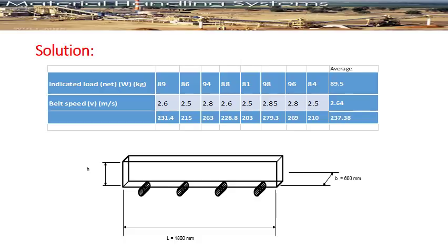So now what we have to find is the height value, which is the height of the material over the belt. We don't know the height, but we know the mass, and we know the density. We have the base of the material because we have the length and the width, and multiplied by the height, we can get the volume.